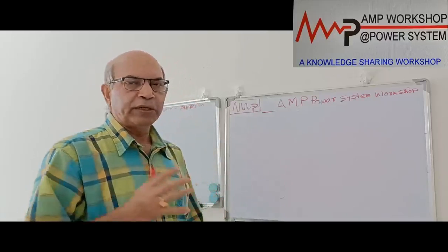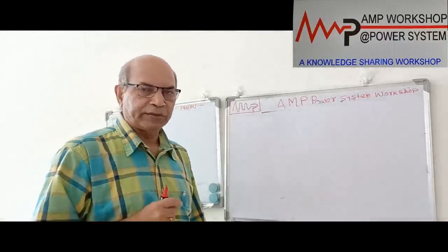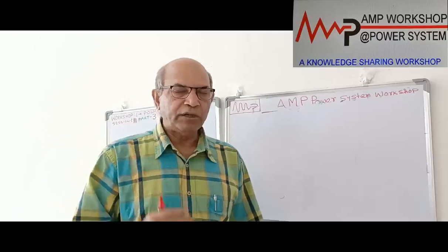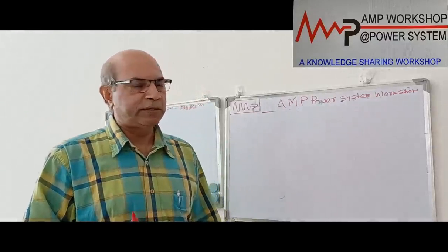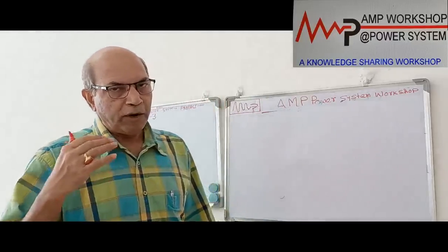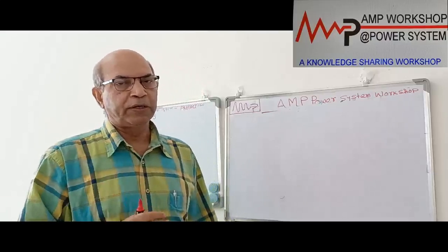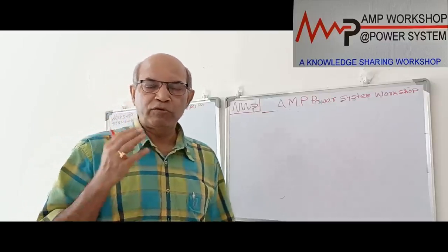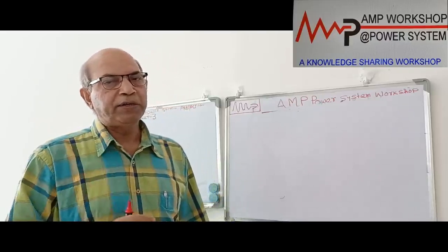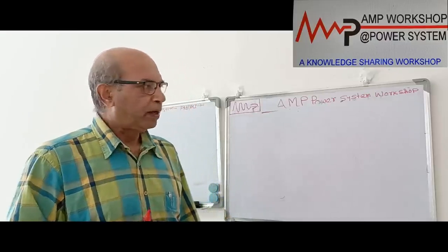In the normal conventional relay, there is no bias characteristic. In the bias differential relay, there is a bias characteristic. But still, the bias characteristic relay cannot completely handle CT mismatch or CT saturation; if CT saturation takes place, this bias differential relay may also operate. To avoid this totally, if we do not want the relay to operate due to CT ratio mismatch, then a new scheme comes, which is called the high impedance voltage differential scheme, or high impedance circulating current differential scheme.